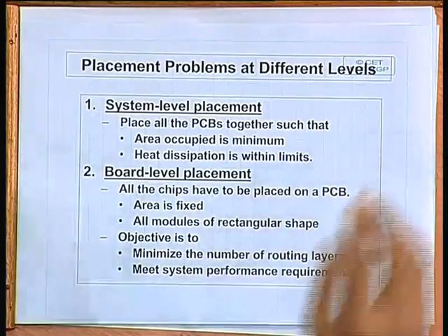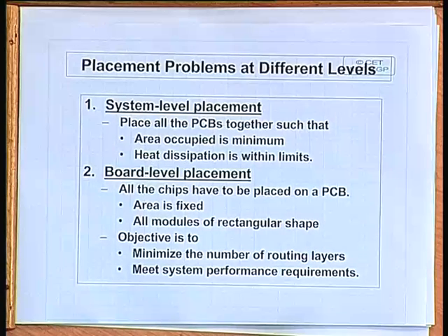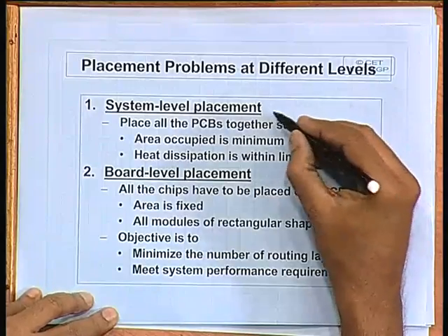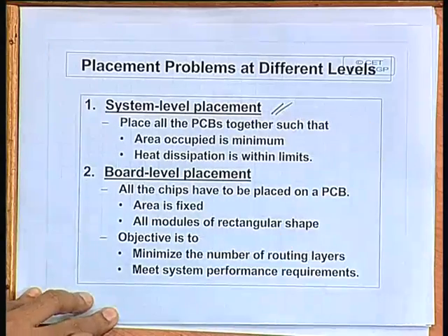Now, in practice you can carry out placement at several different levels. Suppose that your objective is to design a large system, it may be something like a computer system or a dedicated application, where there will be several printed circuit boards going into a cabinet or a chassis, and inside the PCBs there will be ICs, and inside the ICs of course there will be blocks or modules. So, at the highest level you can talk about system level placement.